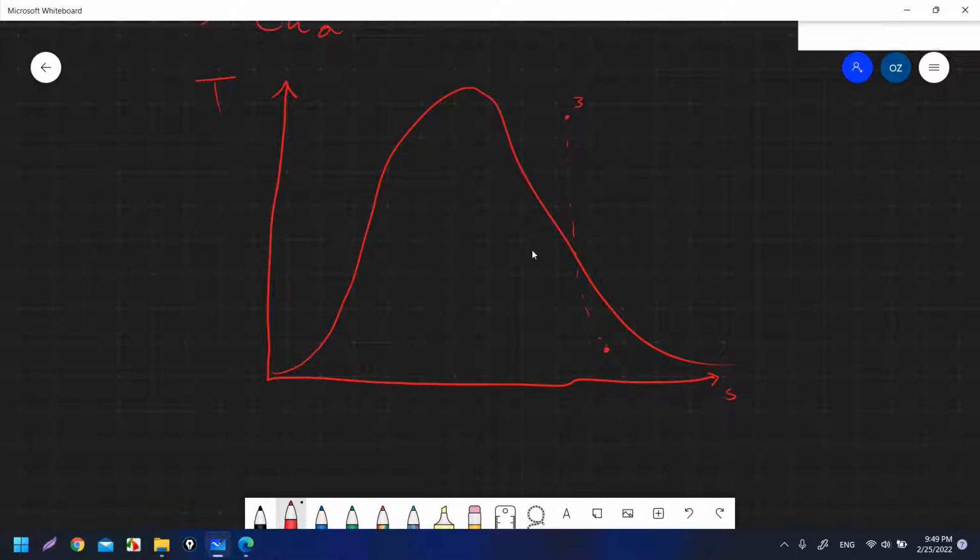This one is 4A, state 4A. But for the ideal cycle, we will go from 3 in a nice straight line. Here, this one is 4S, the ideal isentropic expansion, S3 is equal to S4S. But S3 is not equal to S4A.